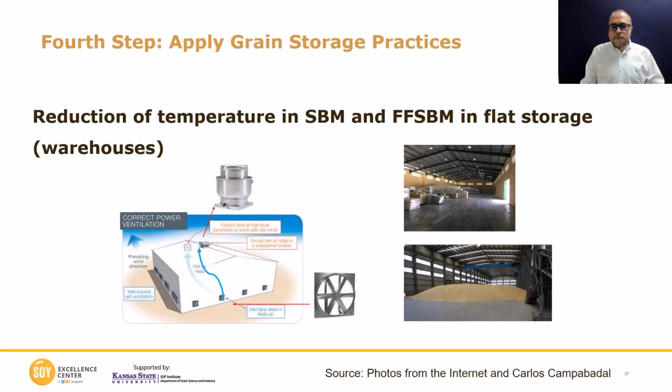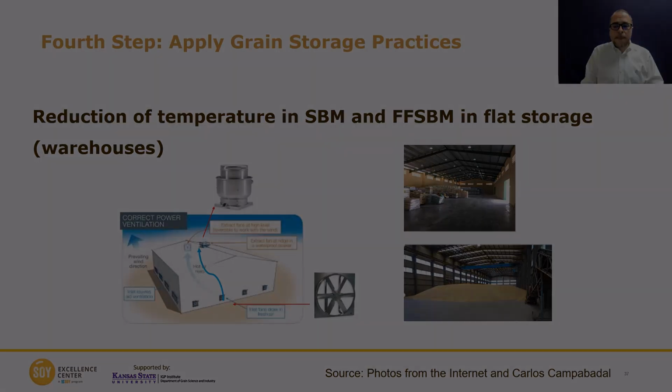If you're storing any type of feed ingredients or grain or oilseeds in warehouses or even bags, it is important to also install those type of exhaust fans so you could keep the air moving to keep the place as cool as possible to avoid condensation problems.